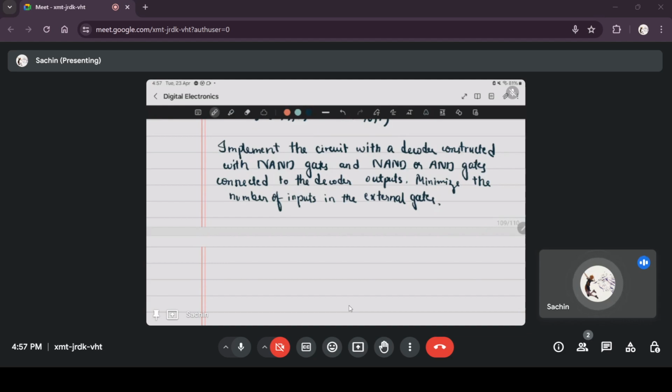From the truth table of the decoder, we can see that depending on the input combination, only one of the lines is high. That means if some minterm is high, so each of the input combinations is a minterm in a truth table, then one of the lines will be high. So each of the outputs of the decoder can be considered to be a minterm.